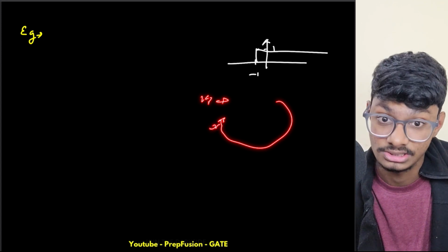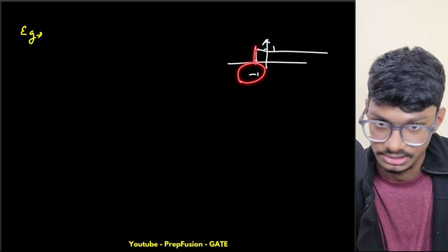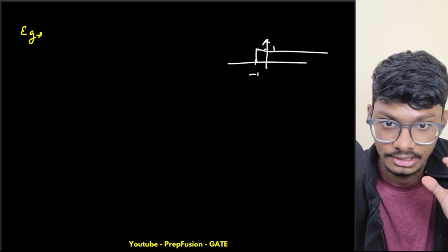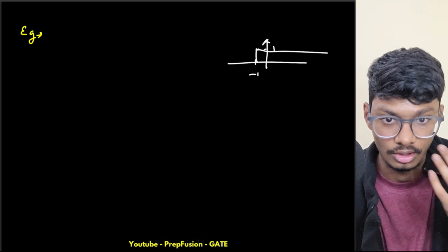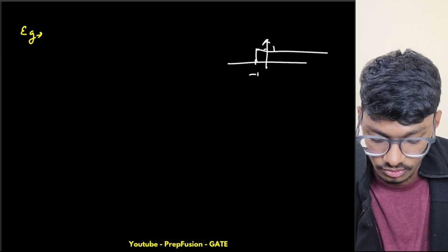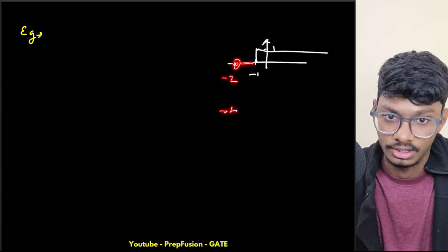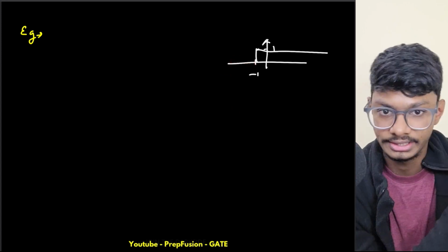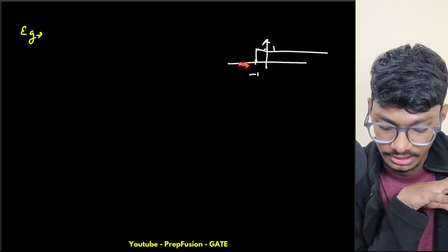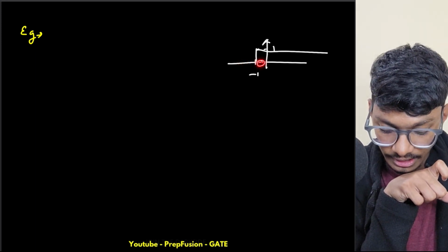Now it reaches 30. If it reaches 30, then my error signal is -1. Now it senses the error signal is -1, so the heater will be off. But as the resistor still has some heat and is still hot, the temperature will still further increase, so the error signal will be something like -2, and it will still be off. Then due to the outside ambient temperature, the room temperature will reduce again, so the error signal will go towards 0. Then when it goes less than -1, it turns on again.